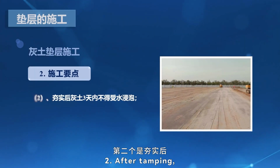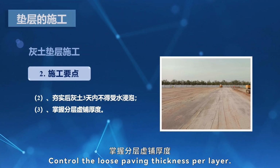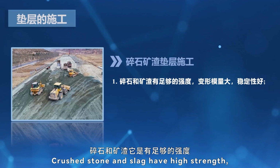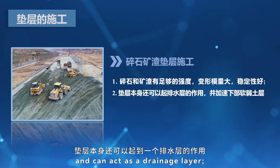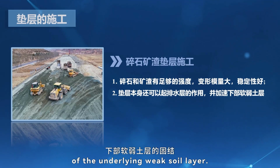2. After tamping, lime soil should not be soaked for 3 days. Control the loose paving thickness per layer. 3. Crushed stone and slag cushion. Crushed stone and slag have high strength, large deformation modulus, good stability, and can act as a drainage layer. They also speed up consolidation of the underlying weak soil layer.